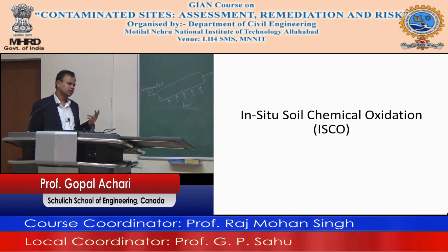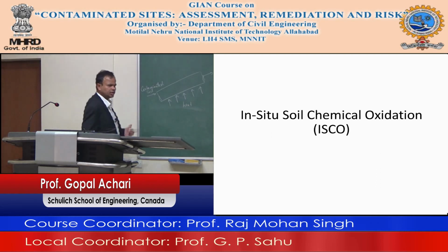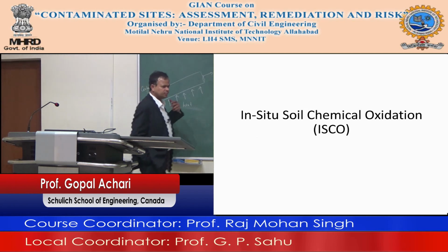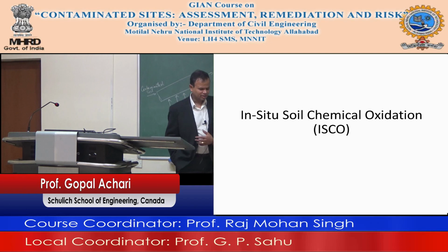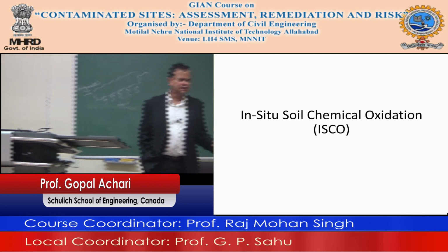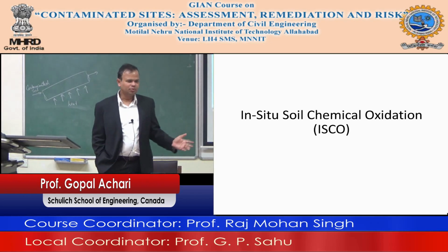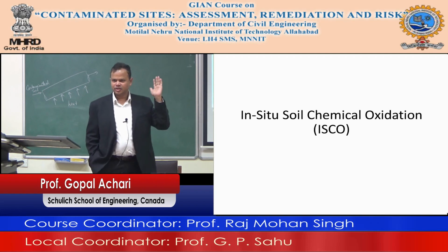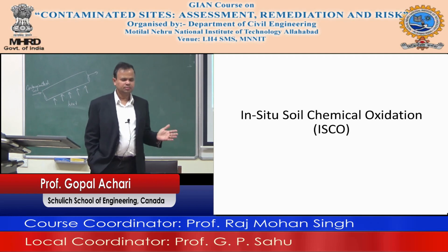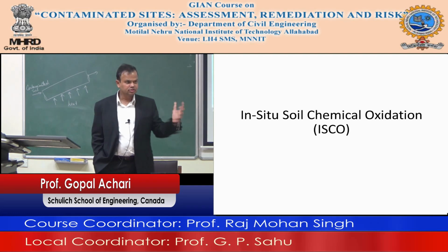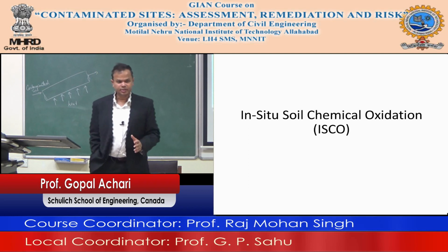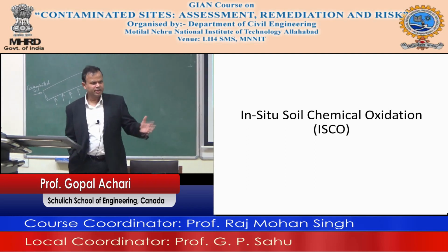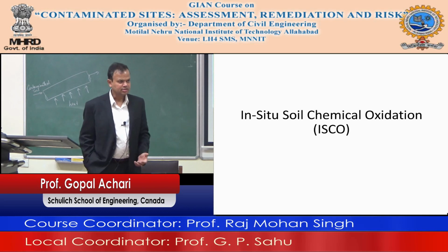In the thermal processes, you can have either a desorber or an incinerator. An incinerator is something that is used for heating and burning the entire soil and everything that comes with it. There are materials like that where you may not like to desorb. For example, hospital waste. The best thing is to send it to an incinerator, let everything get burned, and don't worry about trying to desorb and treat it. But desorption also has a place: lower temperature and of course lower cost.